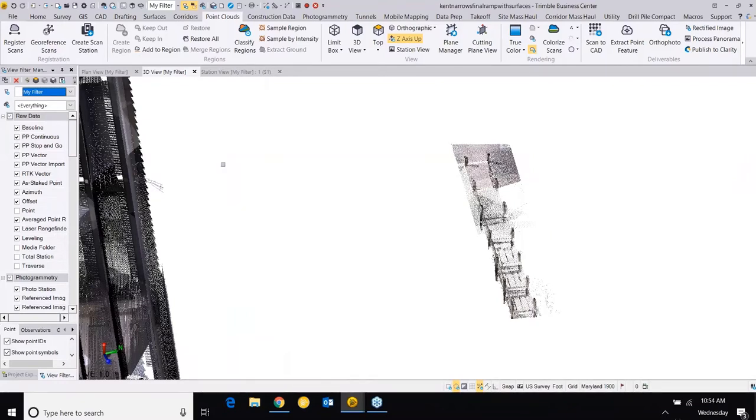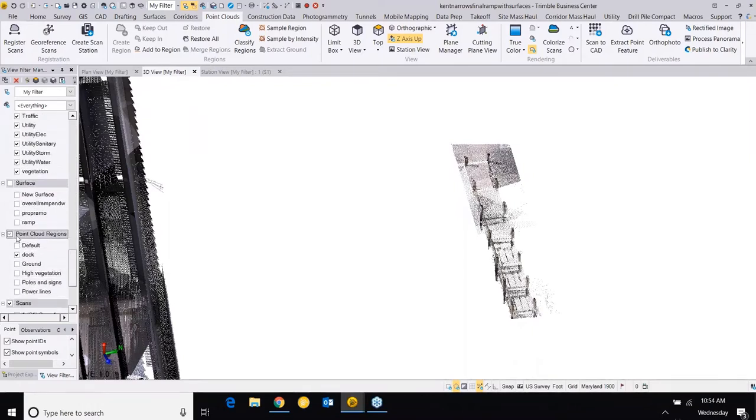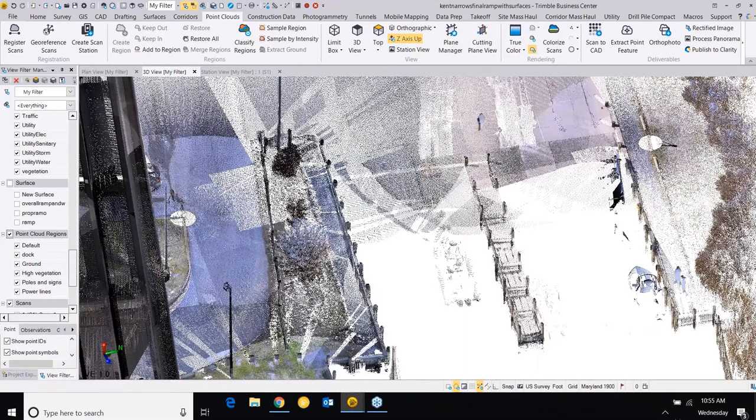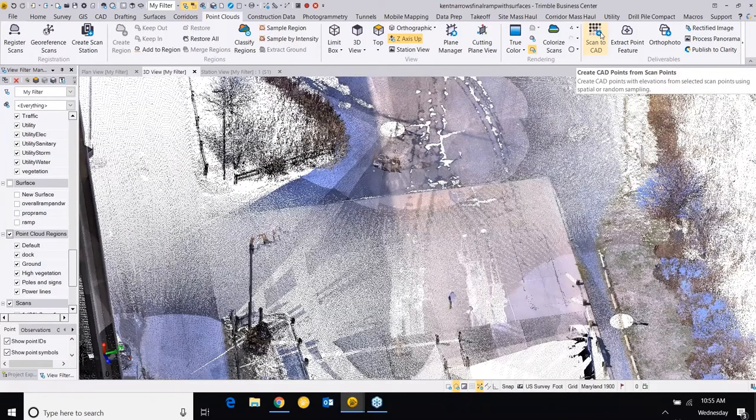Another handy tool and a great observation here was that the density of the SX10 and any terrestrial scanners for that matter, depending on your application, of course, can be managed down. There's really potentially no reason why you would need a point as dense as you've got them collected on the ground, for example. And you can cut using the sampling tools by total number of points in the cloud.